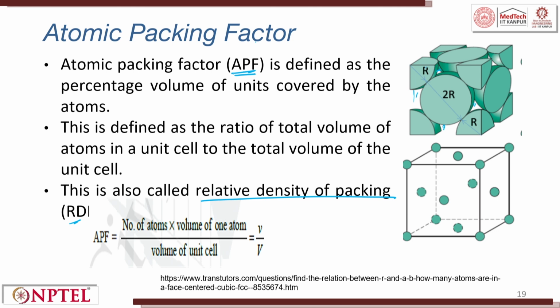So, what is the volume of an atom? This is the volume, right, of the atom. So, you have to calculate the volume of a sphere. Now, the question is whether this atom sitting in the corner is shared with 4 other atoms, or is it sharing with another unit cell only, or how is it? The face where the atom is sitting, is it sharing with another face plane, so that the atom can become half? Here it can become a quarter, here it is half, and suppose if something is sitting inside, it is a full atom.